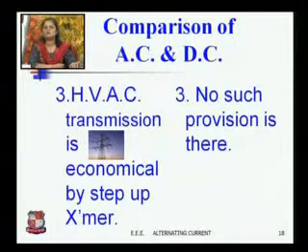Now whenever you consider transmission, the main losses occur in the transmission. These are known as transmission losses, which are I2R losses. It means these losses are affected by the current passing through the transmission line and the resistance of the transmission line. Now as we know, once you design a transmission line, the resistance of the transmission line almost remains constant. You cannot change the value of resistance.